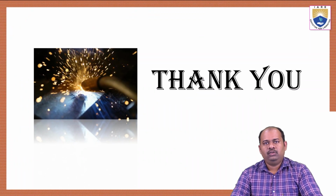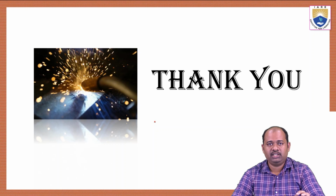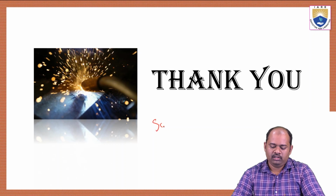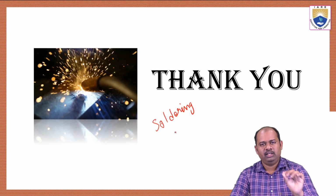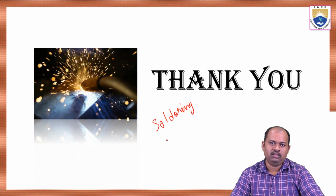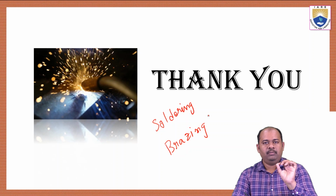So far we have studied two techniques, the two joining processes required in the manufacturing industry. One is soldering, where we use different types of soldering materials and fluxes for joining very weak joints, where the temperature for melting the filler rod is very low compared to welding. Then we have a second technique called brazing, which uses a filler rod made up of different types.